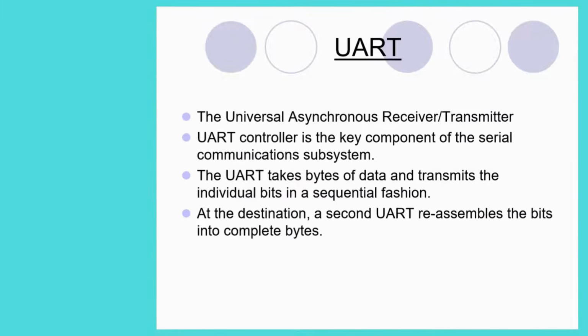The Universal Asynchronous Receiver Transmitter. The UART controller is the key component of the serial communication subsystem. The UART takes bytes of data and transmits the individual bits in a sequential fashion. At the destination, a second UART reassembles the bits into complete bytes.